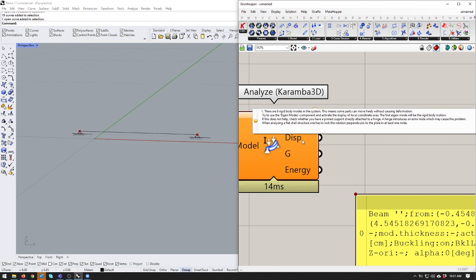If you see this error whilst you're working on this particular set of assignments, then what that means for you is that you shouldn't use eigenmodes. Eigenmodes is like a special calculation mode for what we call funicular structures. These are structures that are flexible and allow more movement than what we would normally see in a rigid system. It means that you can't use the simple finite element analysis calculation methods that we're trying to use here. So eigenmodes run slower.